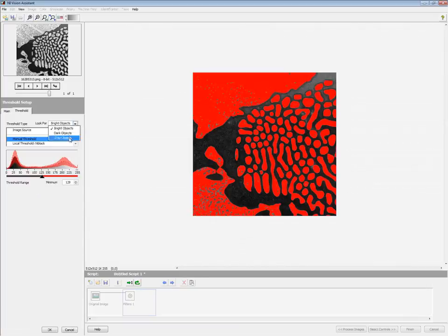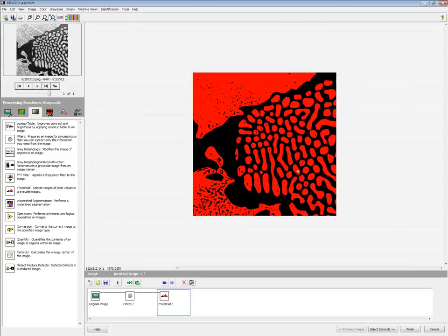So the image that we have is a grayscale image. So we'll use this, and we'll put the minimum threshold value to be 130. That is one of the standards that we use. Okay. Put OK. This is now the binary image. So the red part signifies the pixels with 1 and the black with 0.